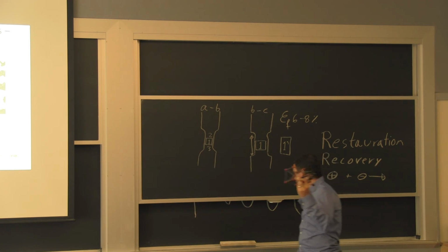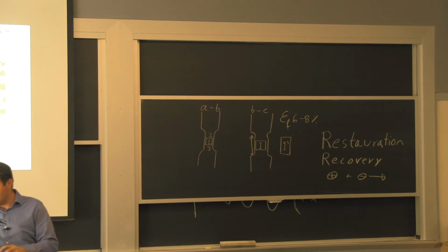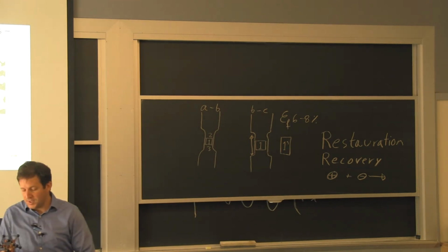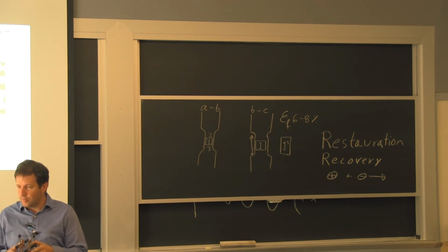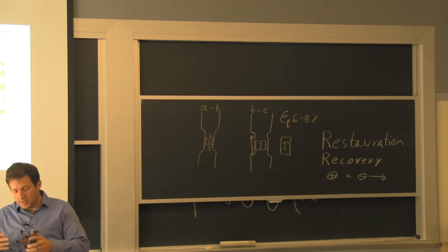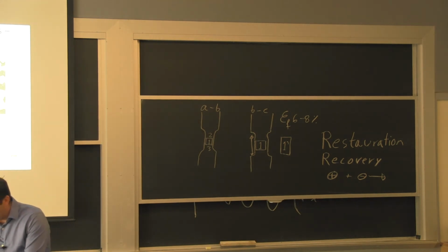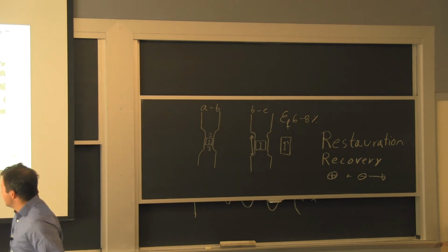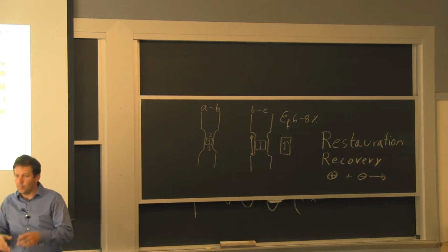This is your crystal. If it's copper or aluminum, it looks like this, but you only have the black items. Just forget about the brown here. What happens is you have 12 ways, 12 slip systems, in which the dislocations like to be and move. So you have one dislocation, another dislocation. They are in so many slip systems. There's only so far that the dislocation will physically be able to move in the grain before it gets too tangled with the other ones. And that essentially defines the spacing here, kind of the free moving distance for one dislocation.